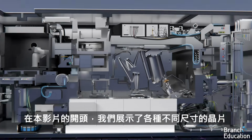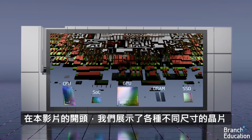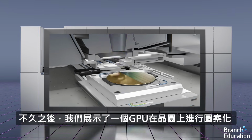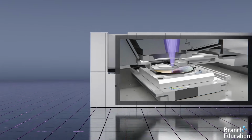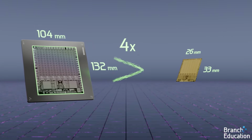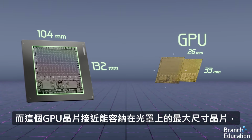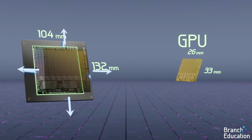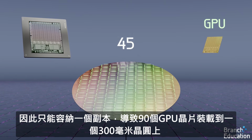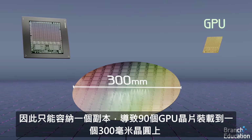In the beginning of this video, we showed a variety of different chips with different sizes, and shortly after, we showed a GPU being patterned across the wafer. The pattern on the mask is 4 times larger than the microchip, and this GPU chip is close to the maximum size chip that can fit on the mask, and therefore only 1 copy fits, resulting in 90 GPU chips fitting onto a 300mm wafer.